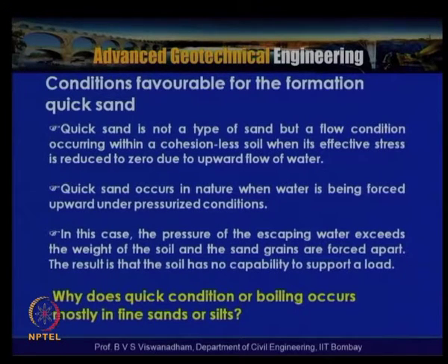Quicksand condition occurs in nature when water is being forced upward under pressurized conditions. Why does the quick condition or boiling occur mostly in fine sands or silts? Because of their low binding tendency.